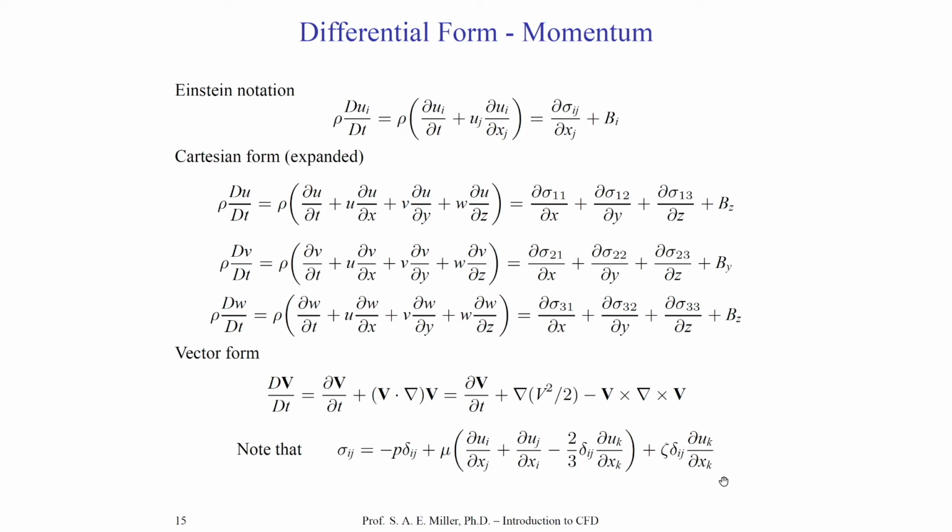So what happens in an incompressible flow that's steady or unsteady? These two terms, the second coefficient of viscosity term and the second term, would both be set to 0. This would mean that only the pressure gradient term and the first coefficient of viscosity term without the negative 2/3 part would remain in the particular equations of motion.